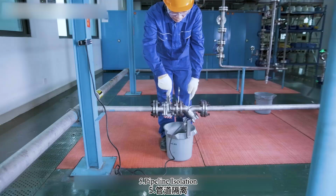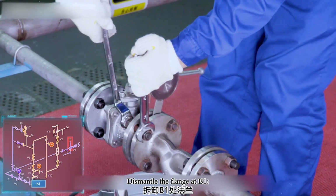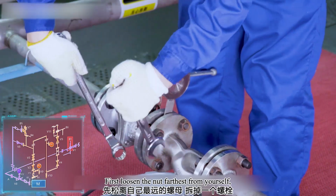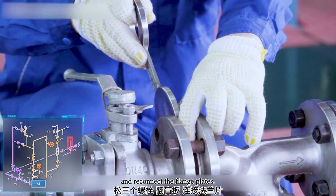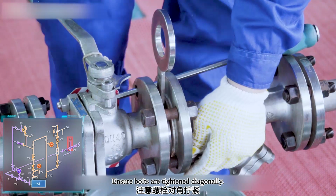Fifth, pipeline isolation. Isolate the pipeline. Dismantle the flange at B1. Note to use the box end wrench in conjunction with the open end wrench. First, loosen the nut farthest from yourself. Remove 1 bolt. Loosen 3 bolts. Flip the blind flange and reconnect the flange plates. Ensure bolts are tightened diagonally.